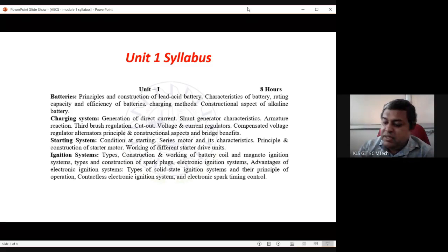In a spark plug, the spark is generated because there are two electrodes having a very small air gap in between. So what we are doing is creating a very huge potential between those two electrodes, so that the air in between actually gets ionized and produces the spark. For a bike, I came to know it when I started my teaching. Mechanical engineering students told me, sir, the voltage in that spark plug is 26,000 volts. So a very huge voltage is produced. But don't worry, it will not give you a shock, because the current is very, very less.